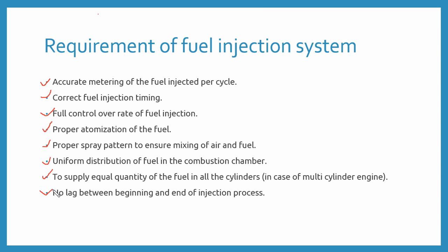So for that reason, the proper injection time is just before the ending of the compression stroke to just the start of the expansion stroke. In just this small period, we need to begin the injection and end the injection. So these are the basic requirements of the fuel injection system.